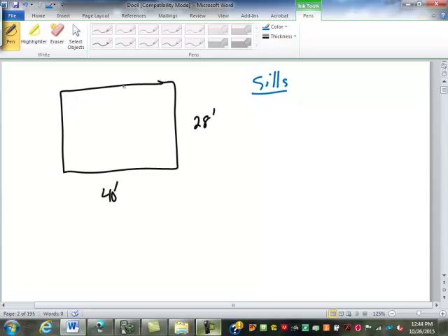That's just the treated board you put on the top of your foundation to build everything onto. We're not going to get into a sill seal or anything like that you would want to put underneath it. We're just looking at estimating the board itself. Some people use a caulking type sill seal. Others use just a roll of stuff that you roll out, the foam type. Caulking is just in a big tube, and you lay down a bead of it. It actually is a better seal, I think, but then if you ever have to lift up one of your sills, it's almost adhered down.